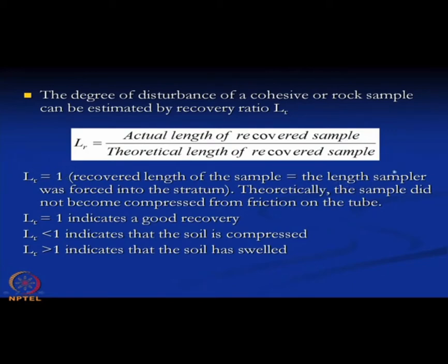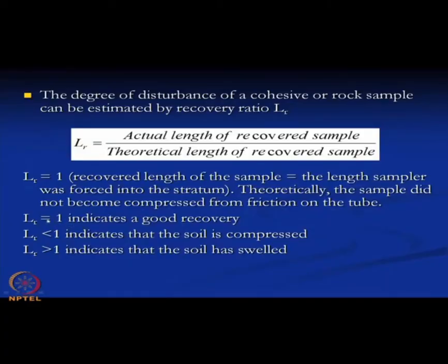If the length of the soil sample we have collected is equal to the length of the sampler we pushed into the soil, then the LR ratio will be 1, and that indicates a good recovery.